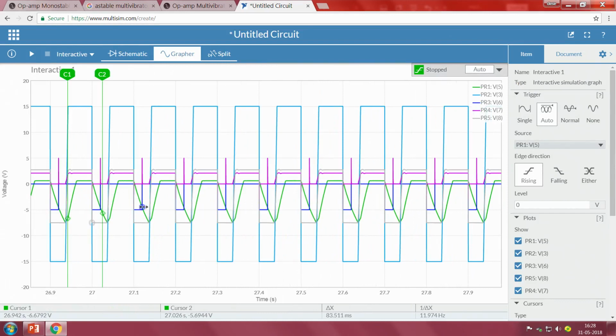That means a monostable multivibrator is not continuously generating a square wave signal; the user has to provide a triggering input to the system, only then does it go to the minus VCC state. Then when the capacitor starts discharging, whenever the voltage is smaller than the reference value, it goes back to its original state. Till the next triggering pulse is received, it will always stay in that state, right.